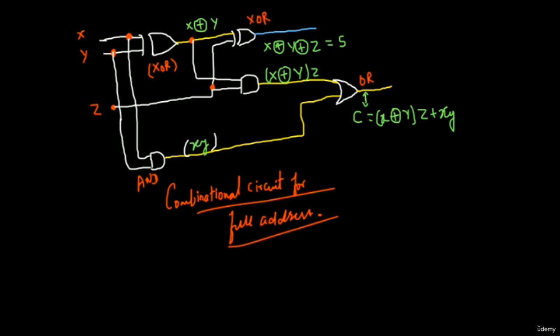Okay, this is going to be interesting one, and this is the AND gate. So looking at this combination, you can clearly understand that we are using 2 AND gates, 2 XOR gates and 1 OR gate. So OR gate is there for the addition, XOR gate is there for the logical addition that we need to do, and the AND gates are for the multiplication purposes, but ultimately we are getting the results.